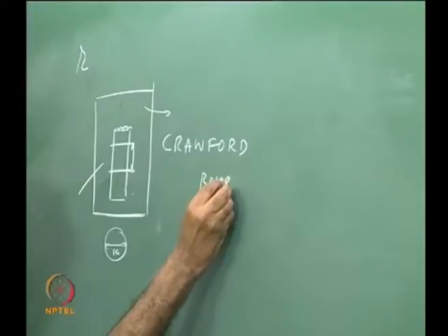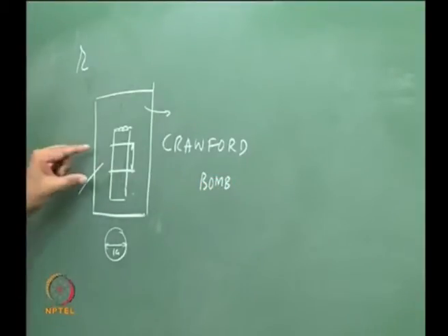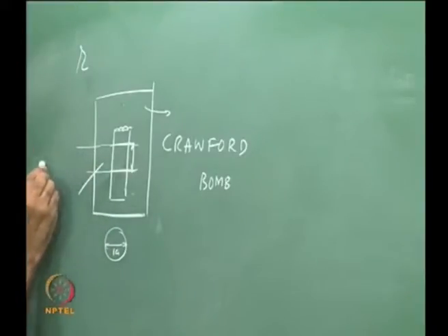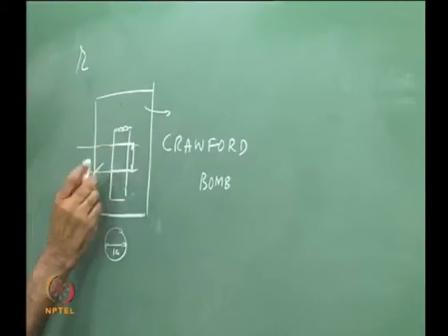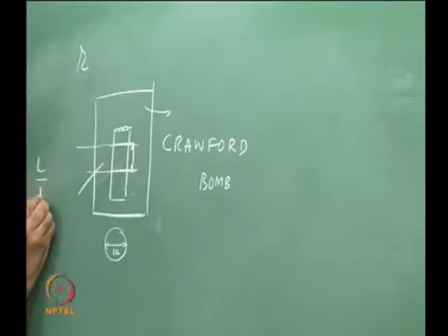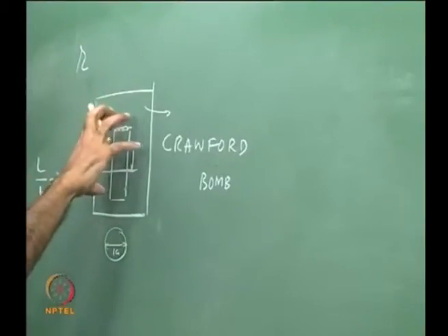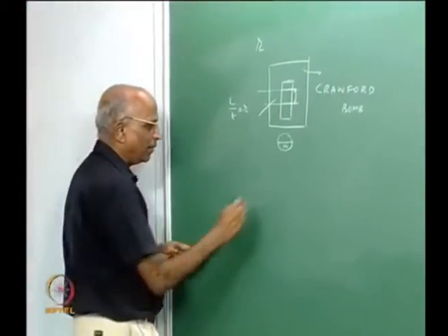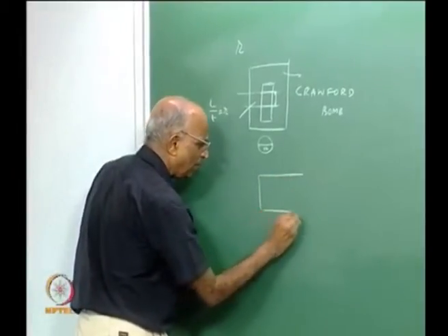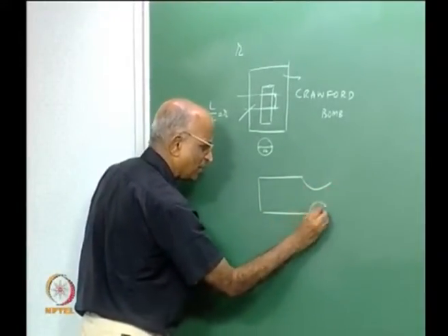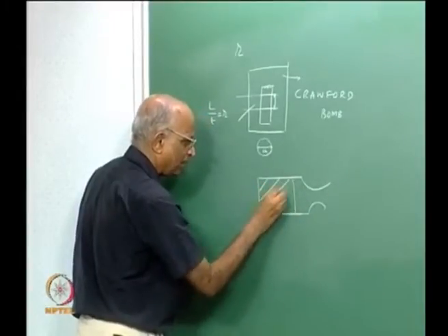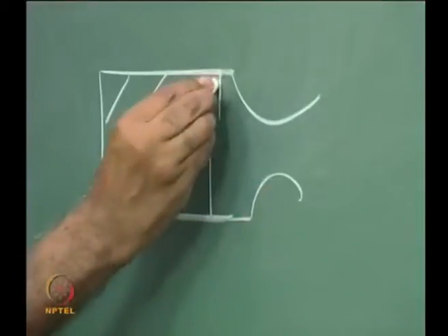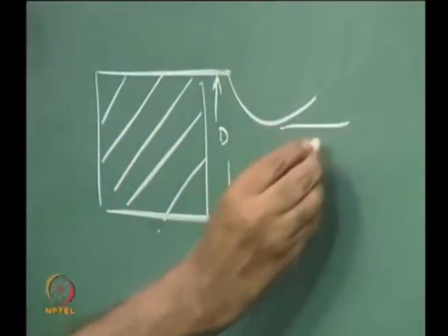It is something like a bomb type of calorimeter in which I burn the propellant, but all I do is put a fuse wire here, a fuse wire here, and give a timer. The timer tells me it starts over here, stops over here, this length is L, and L divided by the time is the burn rate R when the chamber is pressurized to some level. Now I use this burn rate in a rocket motor, and let us say the rocket motor end configuration is like this, and in the rocket motor the diameter is D and the throat diameter is dt.